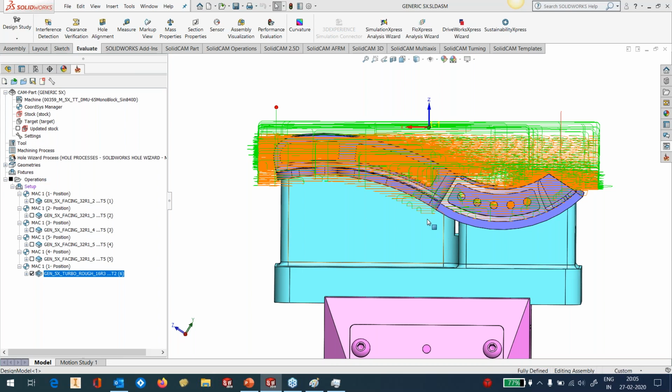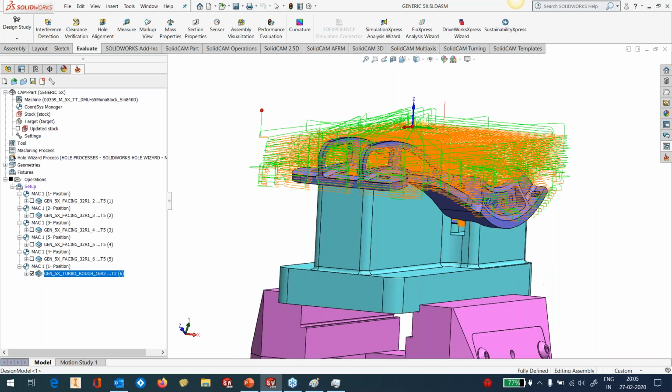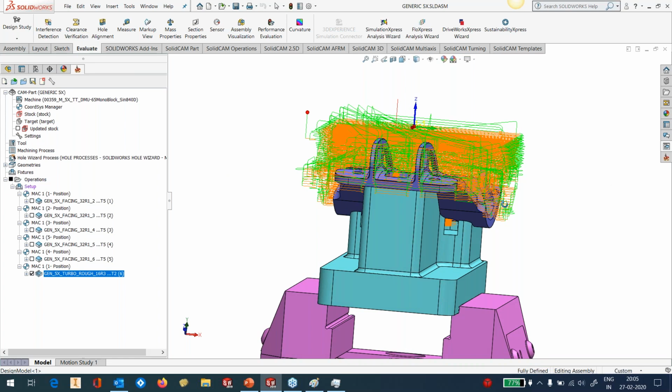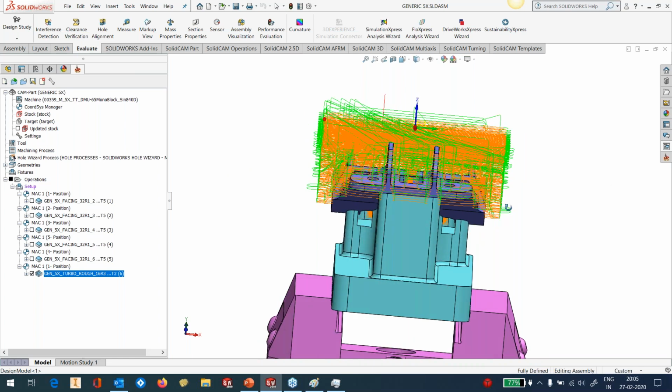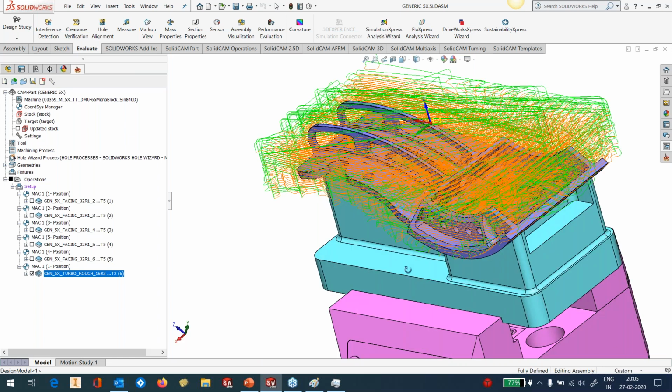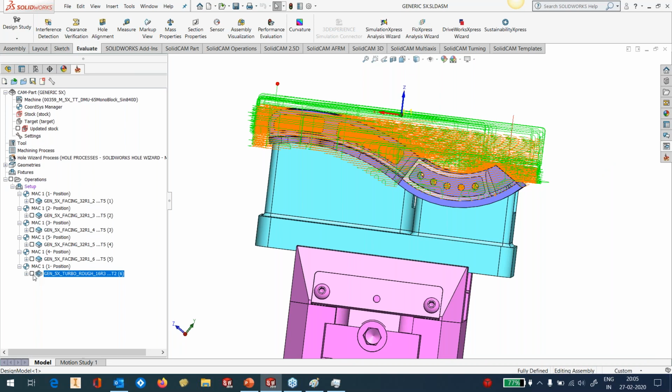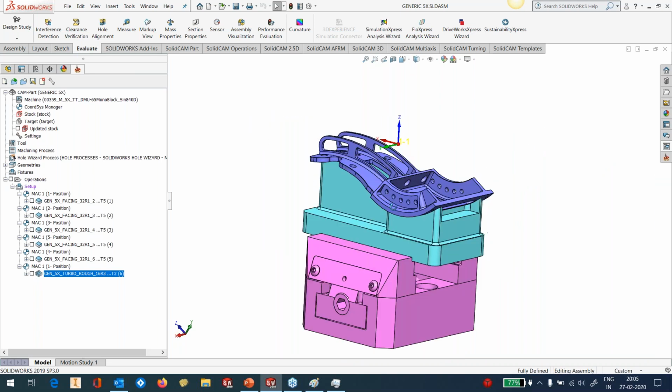The best thing is to generate properly without having to take your scissors and start cutting, because you don't know what the potential hazard of editing would be. So it is a very important and nice feature where it takes the shape of the stock and machines exactly the way the stock looks like. If there's an undercut, it'll exactly stop there. Okay, so let's move ahead.